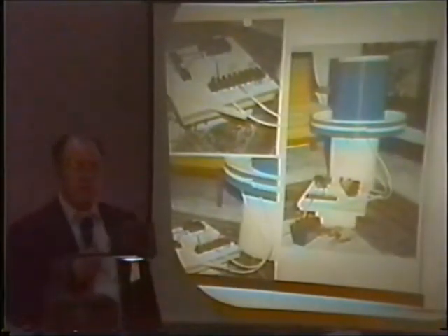It has 3 turns. Your L1 coil's got 3 turns? Yeah, this one has 3 turns of number 8 wire. And the L2 coil has how many turns? The L2 coil has 130 turns on it, and it's number, let's see, number 14, I believe. It's multi-strand wire, because if you use the solid wire, it's very difficult to control and make it look nice. The solid wire goes its own way.